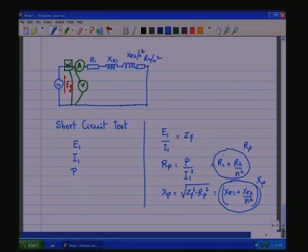R1 can be measured directly from a multimeter. Then R2 can be found knowing N, and in this case we have to take this as an equivalent, the secondary leakage or the primary leakage as seen on the primary side. So, with this we know about the transformer equivalent circuit, the phasor diagram, how to analyze it, and then what are the parameters that come into the imperfect or the practical transformer.